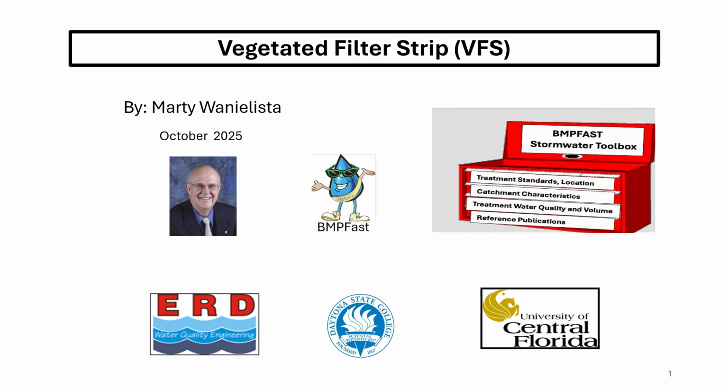A vegetated filter strip is a recognized best management practice included in the applicant's handbook under Green Stormwater Infrastructure. These systems are typically found adjacent to impervious surfaces like highways and parking lots, and they are commonly applied in high water table areas where groundwater percolation is returned to a surface discharge.